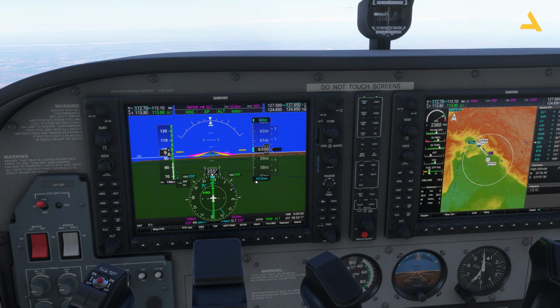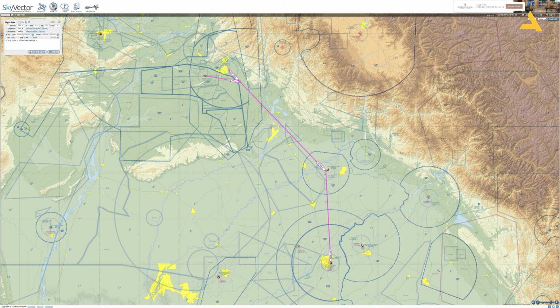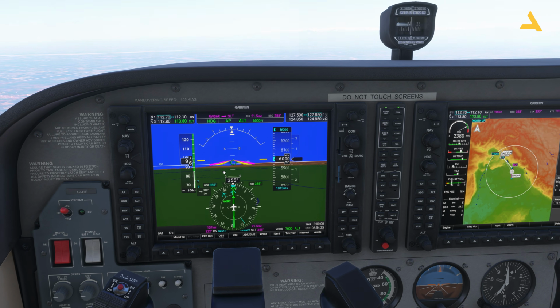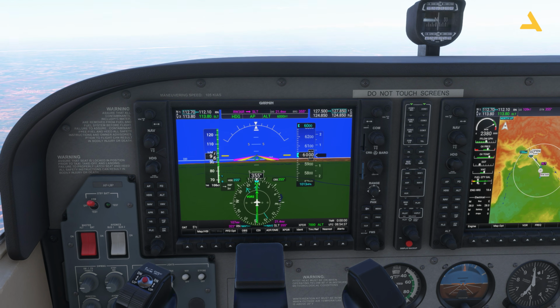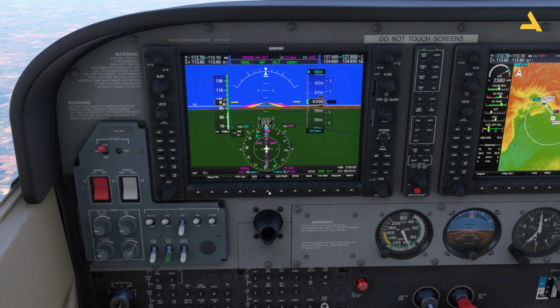And let's go to Skyvector. Now the Skyvector tells me that once I am at Sialkot VOR, when I cross it, I then have to fly in this heading 315 degrees. So my course is 315. So go back over here, and for VOR, right now this is VOR 2. I'm tracking Sialkot. So I'll press CDI once again, and then now it's 315. So I will just adjust the course 315 over here.